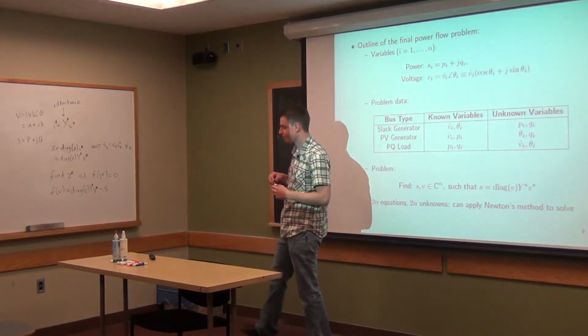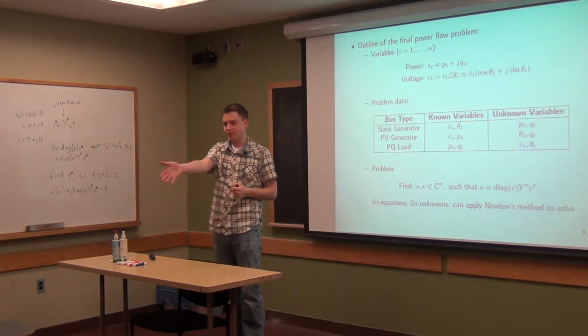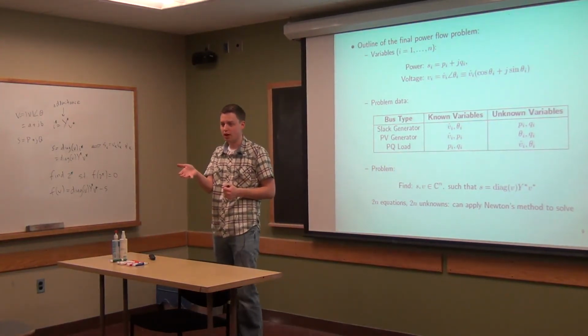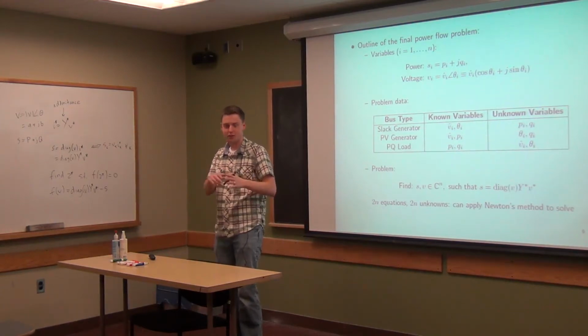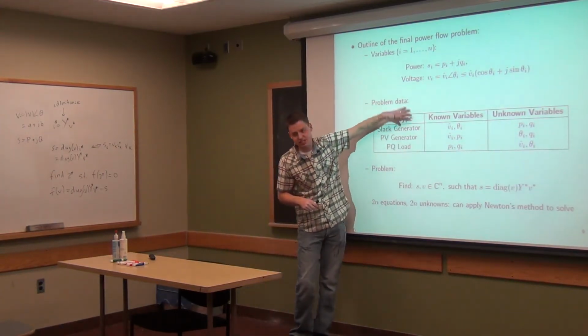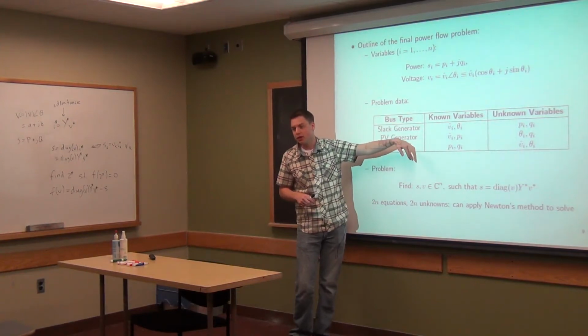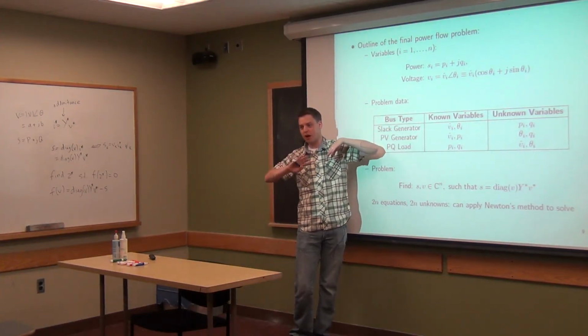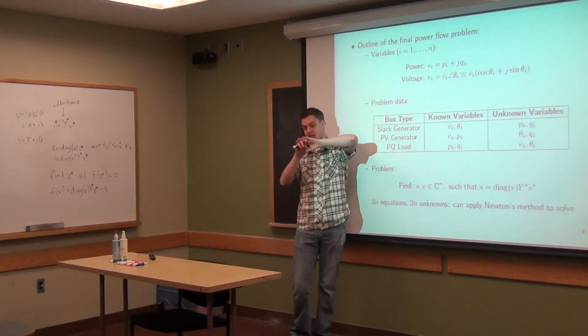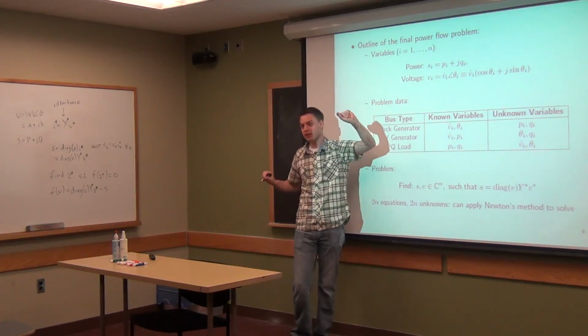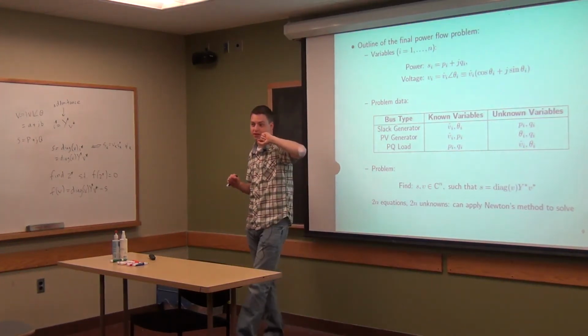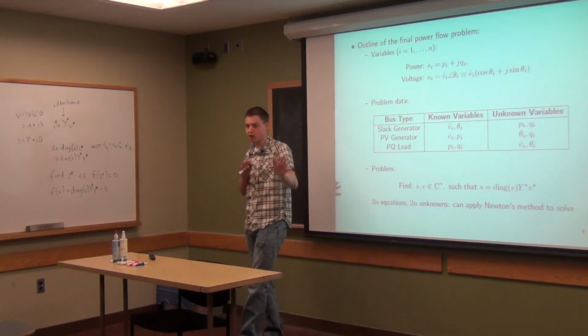Because when you have a reactive power, for example, because you have some inductance in your line, that voltage angle could fall behind the voltage angle of a generator that's not behind that long line with high impedance. So you will have different voltage angles at different points in the network.